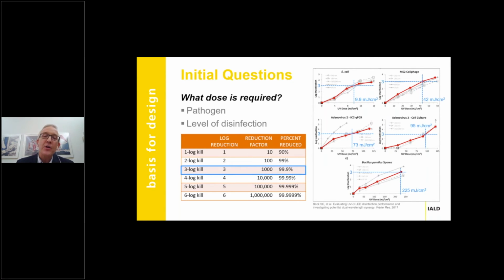Also, note from the chart that no level of disinfection eliminates everything. In all cases, there will be some portion of viable pathogen remaining. UVC systems do not kill and deactivate every instance of the virus or the pathogen. GUV should not be referred to as sterilization, and you should not guarantee that your designs completely eliminate the threat. Chances are that GUV is only one of the disinfection countermeasures implemented on a project. It's a good one, but it's not the end all.